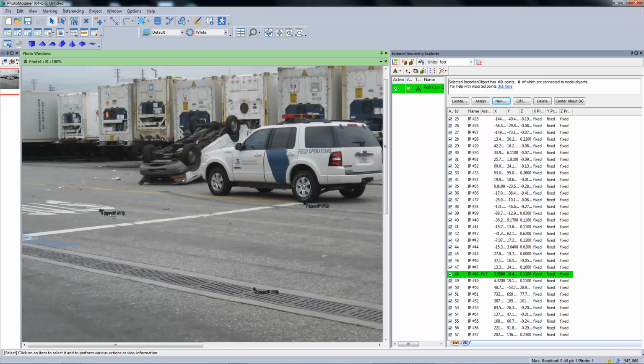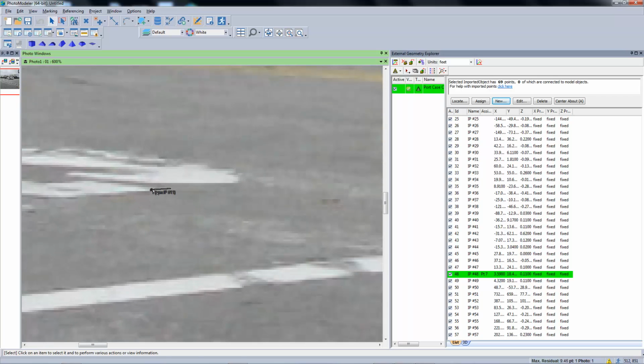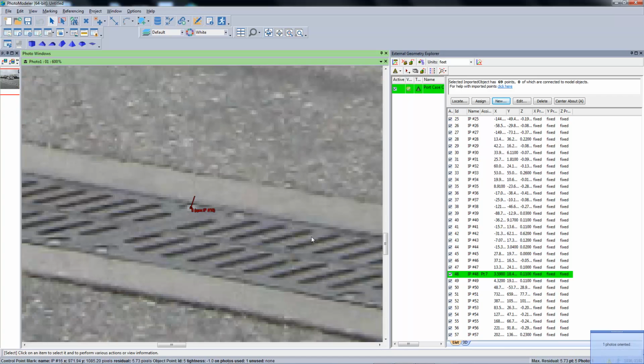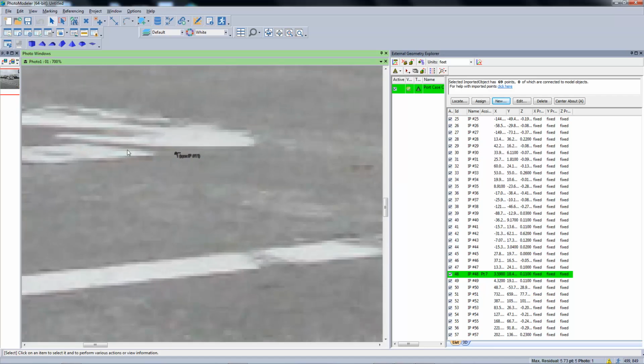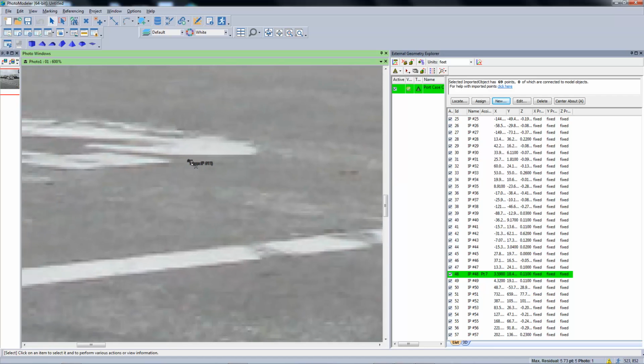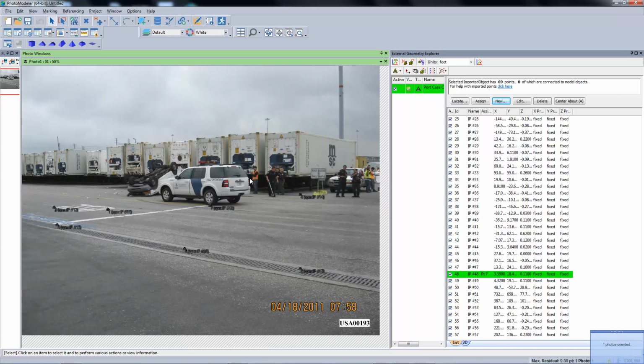And you can go around and kind of monkey with these things a little bit, but you don't want to go anywhere that doesn't make sense. So if I put it here, sure, I could get my residual down to 5.73. But at the end of the day, that doesn't make any sense. If somebody else is looking at this project, they're going to say, yeah, your residual is 5.73, but it's bogus. This point should be over here. So the actual residual is something like 10.4, 9.8, somewhere in that ballpark.